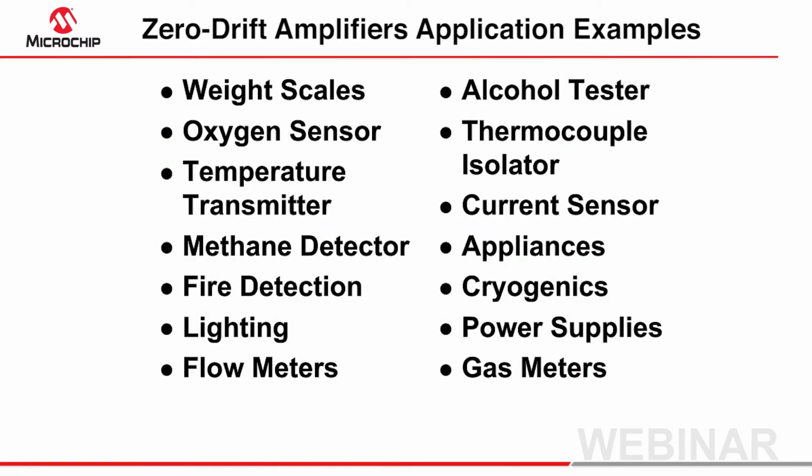Due to advances in processing capabilities as well as silicon design, zero drift amplifiers have become not only easier to use, but also are becoming more cost effective. This has led to a wide variety of devices spanning from low power to wide bandwidth offerings. As zero drift op-amps promise to make life easier for system designers, it's no wonder they are getting increased attention from all industry segments, including automotive, medical, industrial, as well as consumer applications.